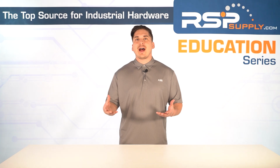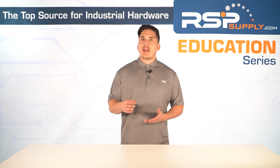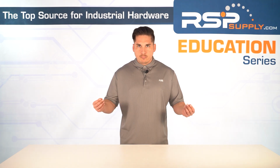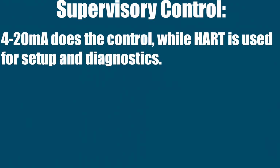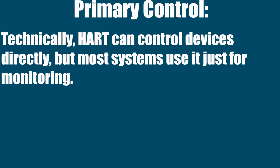HART protocol, that's a hybrid. It's analog and digital. It uses a standard 4 to 20 milliamp signal for real-time control, but adds a digital signal on top. There's two ways it's used. For supervisory control, which is the most common, 4 to 20 milliamp does the control, while HART is used for setup and diagnostics. For primary control, it's a little bit more rare. Technically, HART can control devices directly, but most systems use it just for monitoring.